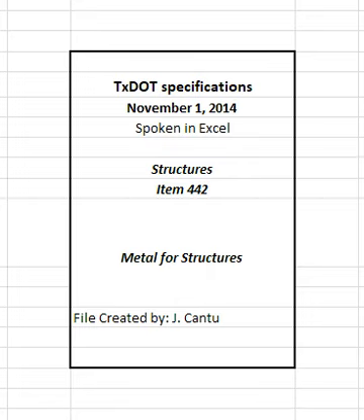2.4 Iron castings. Provide iron castings that are true to pattern in form and dimensions, free from pouring faults, sponginess, cracks, blowholes, and other defects in positions affecting their strength and value for the service intended, and meet the standards shown in Table 3. Table 3. Standards for iron castings. See table in specifications.